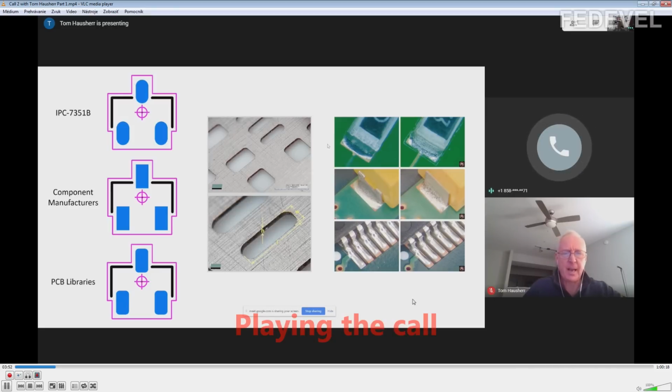If the component manufacturer recommends it, you can go ahead and use it, but you're still going to get rounded rectangular stencils, and you're still going to get no solder in the corners. But it's okay to use them. But we need to say this is only for very small dimensions when it actually is really visible. For bigger parts, it doesn't really matter. Well, I'm going to go into that here in the near future, about why you have to use rectangular pad shapes in some cases.